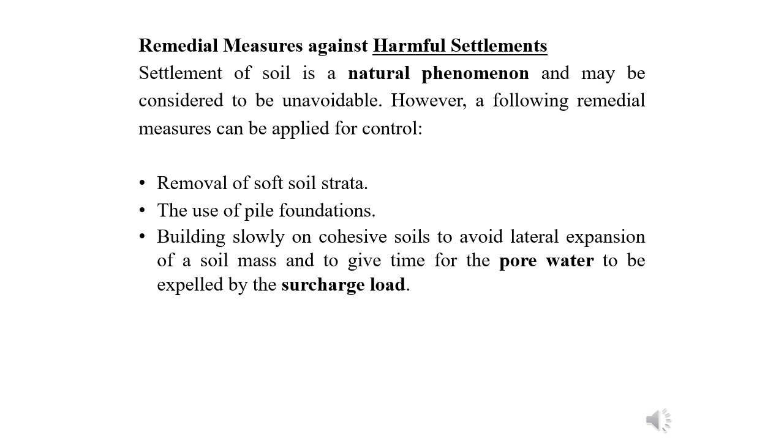The third point is that if you are going to construct the structure on cohesive soil, in that case, how can we avoid the lateral expansion of the soil mass? For this, we can give some drains so that from the side of the structure, the pore water pressure will be released, or pore water pressure will be expelled. In that case, what will happen? The structure will come on the solid particles.